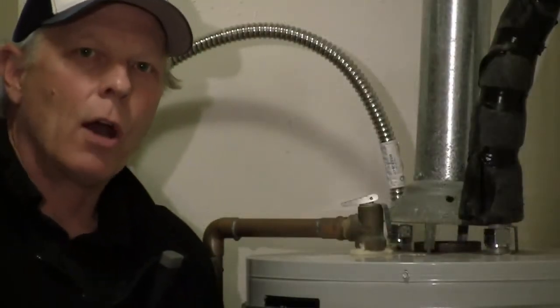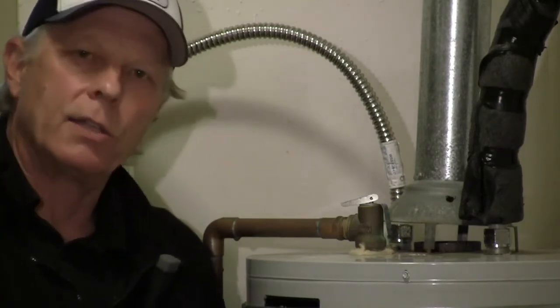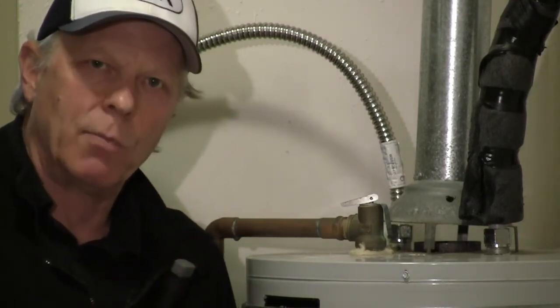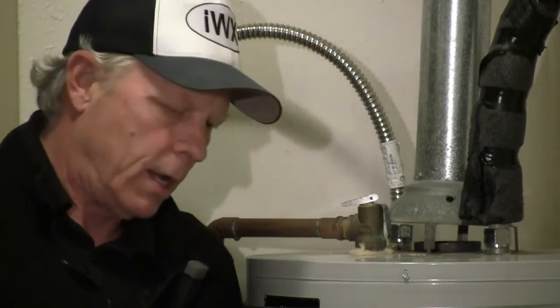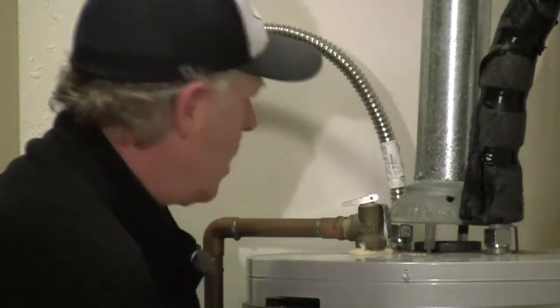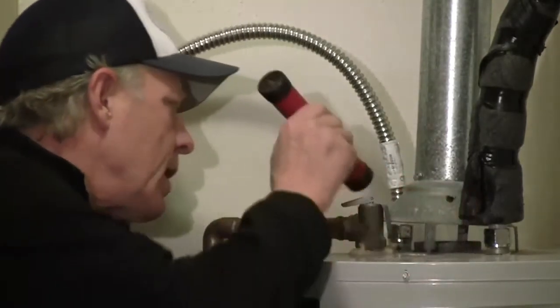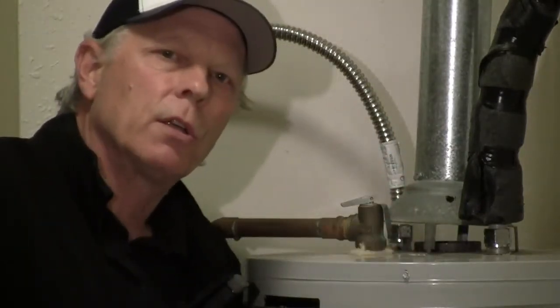Okay, I turned the water heater on. It's been running for about 1:45. I had set my timer for 2 minutes. 2 minutes is the current ANSI BPI 1200 limit for spillage for a warm vent. And now it's been 2 minutes. I'm going to go ahead and check with smoke around all sides of the draft hood. And there is no spillage. So this water heater passes the spillage test.